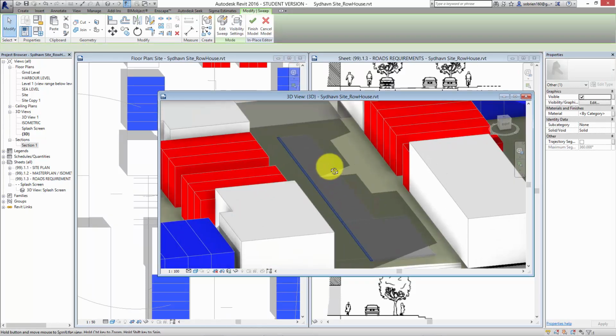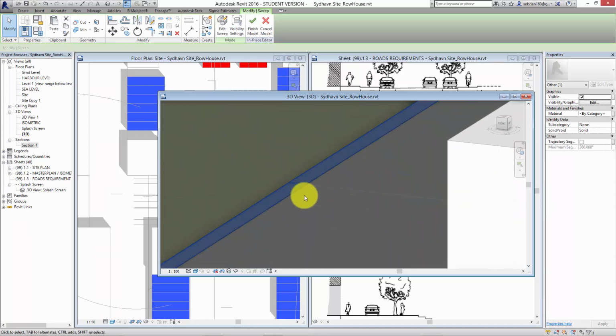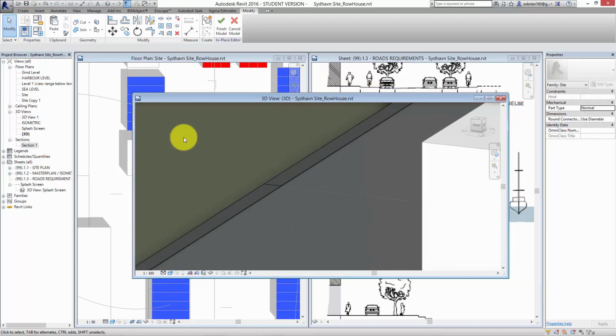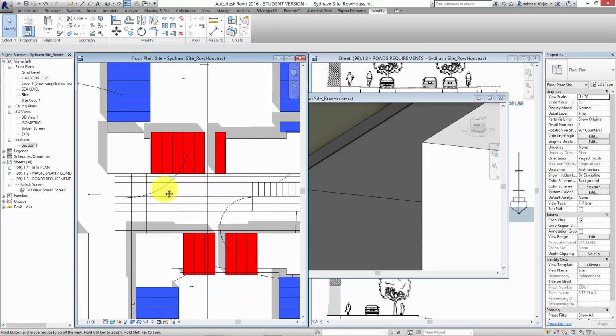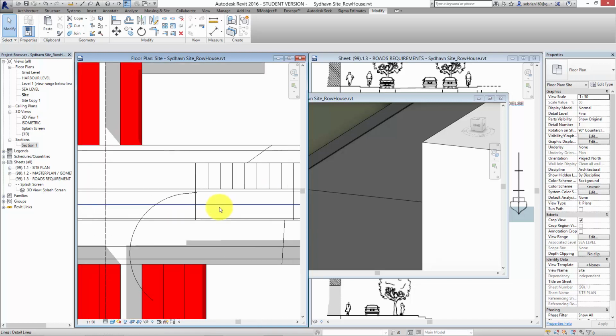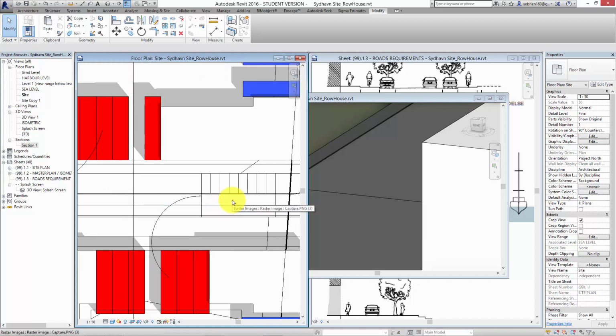it will create a sweep following the line of where we want it to go, but it will follow the modifications in the slope, so that the whole road will move together as a kind of contiguous thing. Does that make sense? Okay. Now what I'm saying is that the 3D elements of the site are not as important as actually getting the annotations down. Actually starting to work out how the different things are set up is more important than the 3D elements. But you can get to a point where you actually want to add it in 3D, because after a while you can calculate the excavation and the amount of material in the road that you need to add to it.